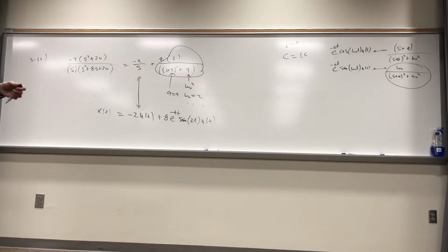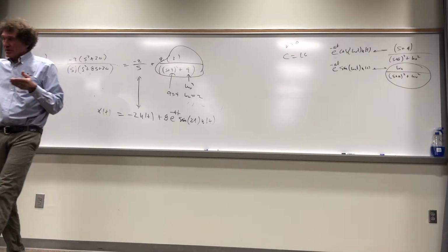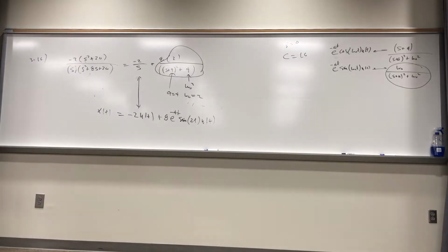I just have a comment about that. Yeah, go ahead. So if you find the roots of the denominator and then substitute the roots and express the answer... But the roots are complex for this one. You have conjugate pairs. Yes. So then you would have A over s minus the first pole, plus A conjugate over the second pole. Yes. Then you're going to express it in polar coordinates. Wouldn't that be more straightforward? You don't have a calculator to calculate the angle. You can't get that with pen and paper for anything but a simple thing.